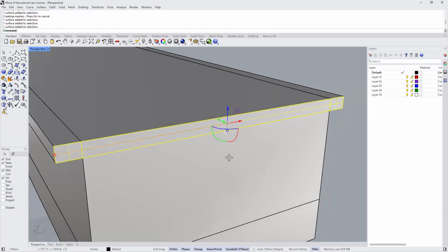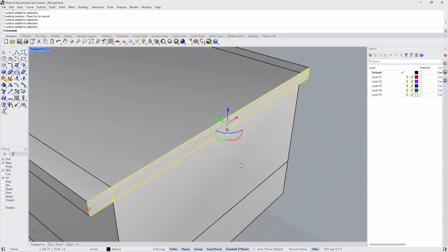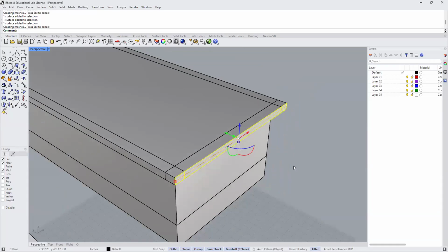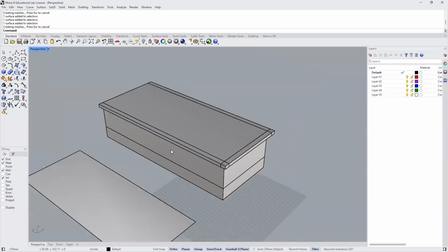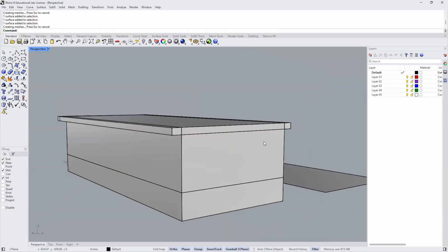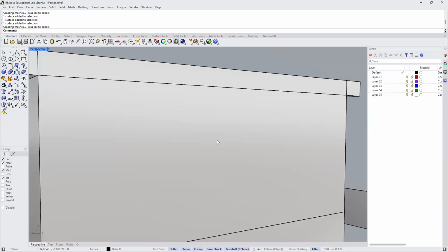And then I'm just going to orbit a bit like that. And then I need to extrude them along the green axis. And the green axis, I have to now type in a value that is negative. So I'll click on the dot, and then it's already set to minus 1'6" based on the last entry. So I'll just enter. And that's all set. Click off of it. And then I'll orbit to the backside. And I'll do the same thing here. Just position myself in a way that I can see all 3 of these surfaces. Get a little bit closer.